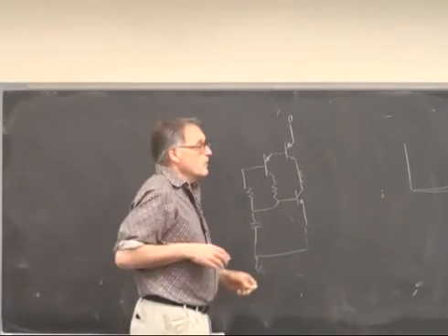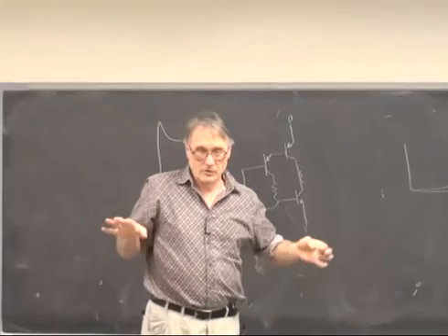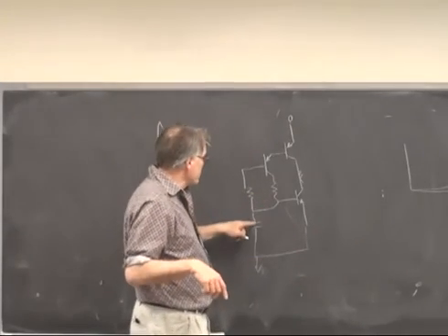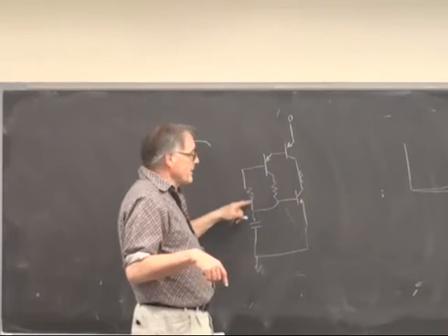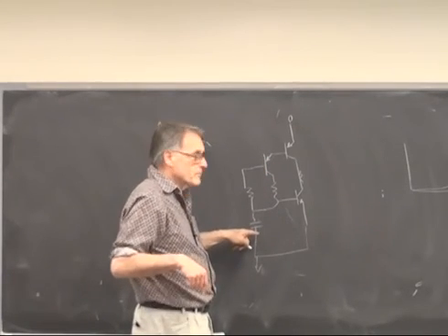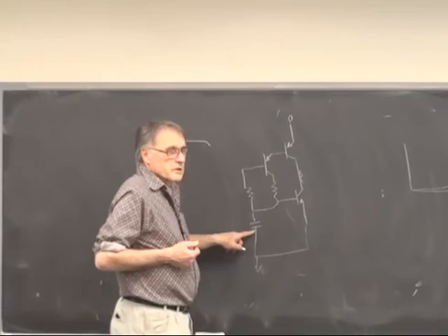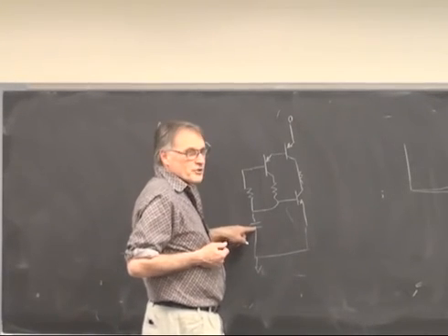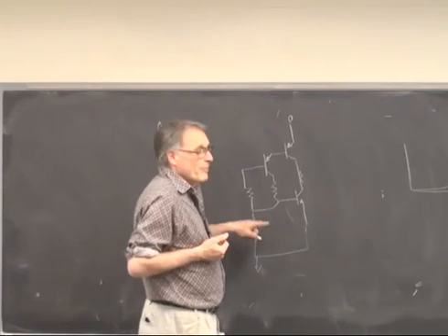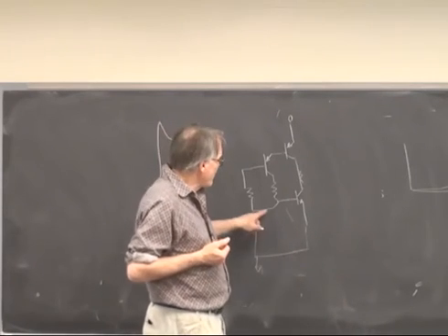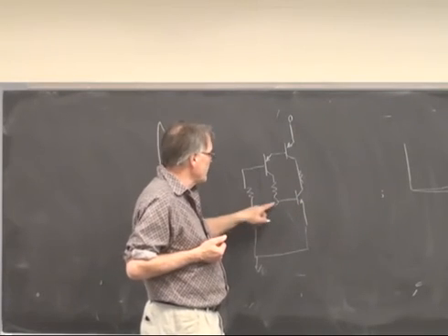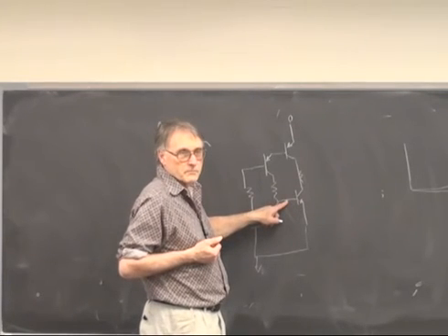Okay, so nothing at all happens until the voltage gets up to about 1.4 volts. Then this capacitor starts to charge because current finds its way through here. It keeps on charging up to about 0.7 volts or so. At around 0.7 volts, this transistor turns on and latches this voltage at 0.7 volts.